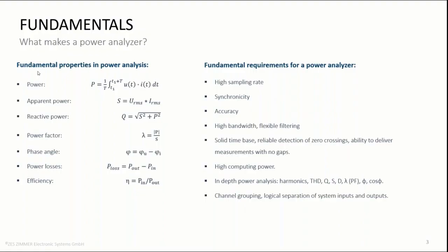Of course, even when the above applies, the measurement in the end can only be correct if the actual values of the voltage and the current signals are correct. So here we are talking about measurement accuracy, and this is why precision power analyzers have very tight specifications on their measurement uncertainty. Measuring the power, as explained right now, together with determining the RMS values of voltage and current, basically lets us calculate most of the electrical properties that we see in this slide.